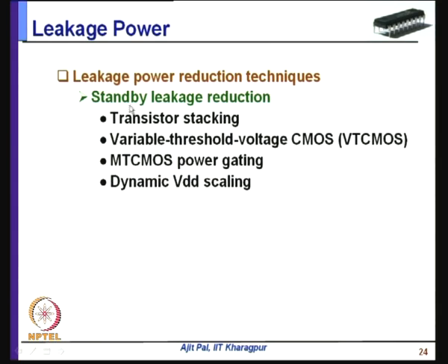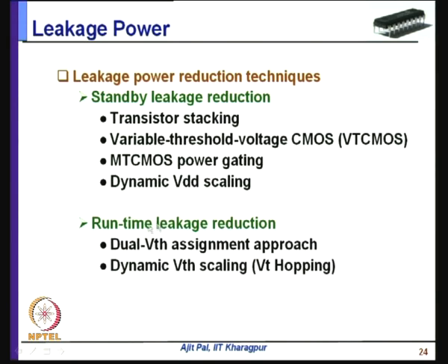Under the standby leakage reduction techniques, we have discussed various approaches like transistor stacking, variable threshold voltage CMOS, VTCMOS, then multi threshold voltage CMOS, power gating, and dynamic VDD scaling. Then you can go for runtime leakage reduction techniques.